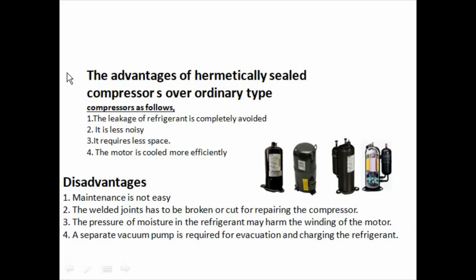Let's now move from the advantages of this hermetic compressor to its disadvantages. Point 1, maintenance is not easier. As we know, this compressor is very well sealed and welded, so during maintenance it will require you to take a cutting machine or an angle grinder in order to cut this case, which is very hard to cut.